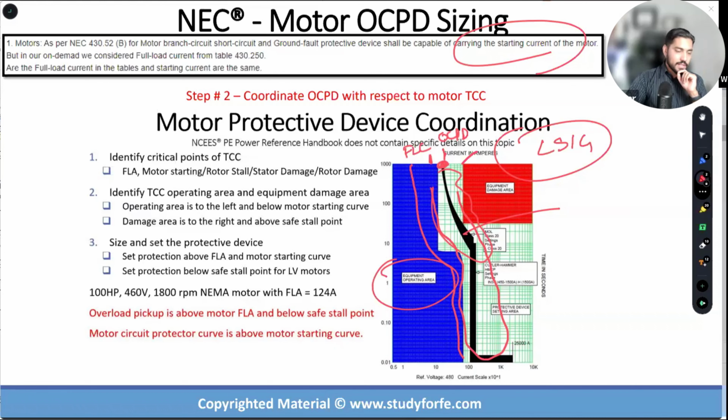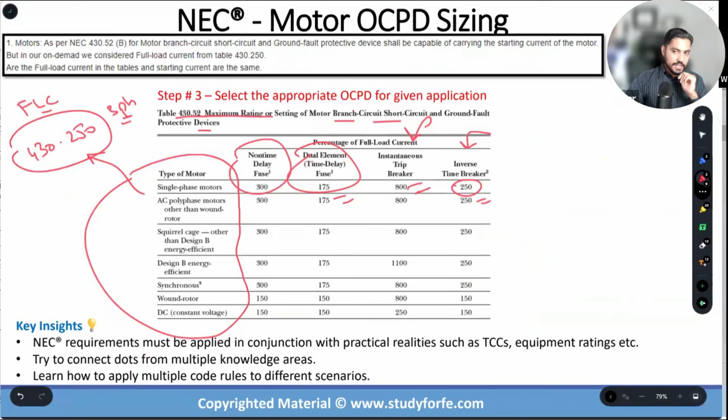And what the code is, in layman's terms, telling us is that with that trigger, you have the flexibility, and remember this is the maximum. You have the flexibility, you have our blessing, you have our permission to start that trigger up to 250% of your motor FLC if you want to. Does it make sense? And then once you push it to the right to 250%, if you're dealing with the inverse time breaker or instantaneous trip breaker, these are high because instantaneous is boom.